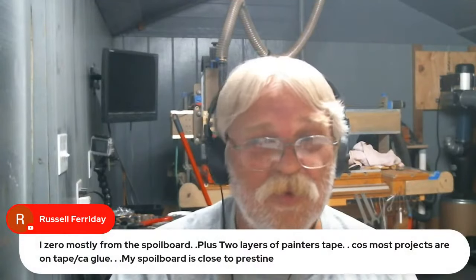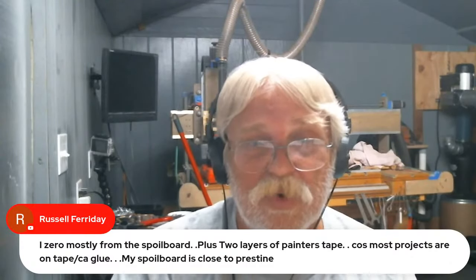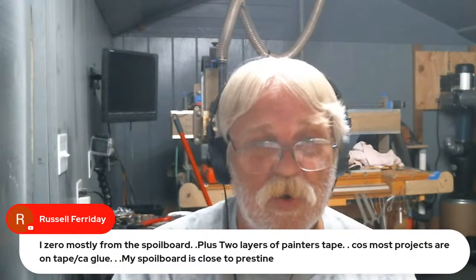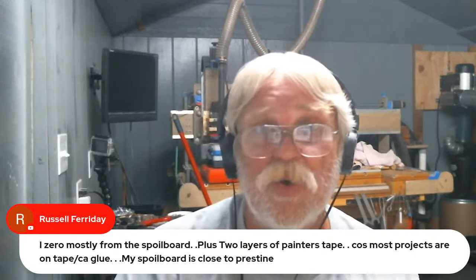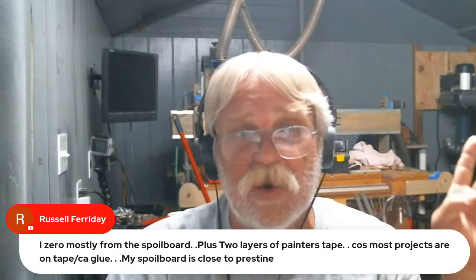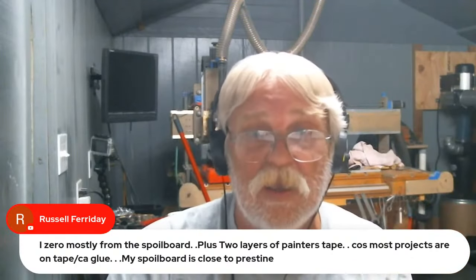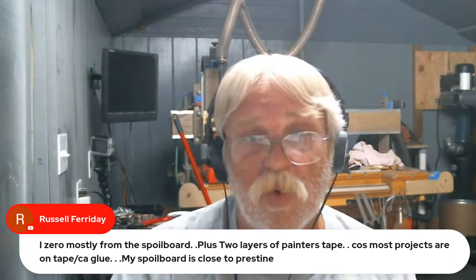So let's see. Russell Faraday says, I zero mostly from the spoil board plus 2 layers of painter's tape because most projects are on tape and CA glue. My spoil board is close to pristine. Yeah, I know a lot of people do. Peter Pasuelo over on his channel, CNC Nuts, that's his go-to. He mainly sets his Z0 and references off of the spoil board.